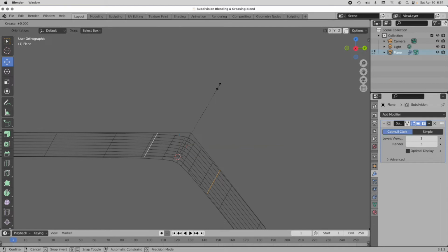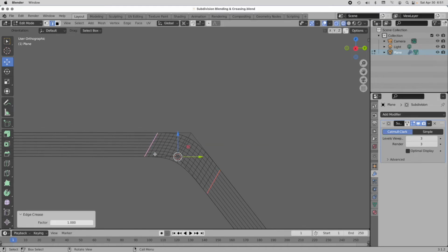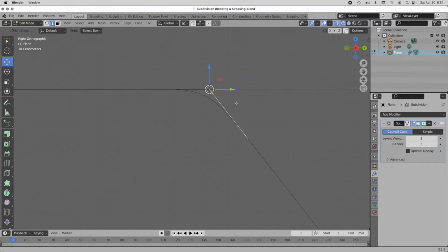So I'm pressing Shift and E, and you just mouse until you see those subdivided polygons only sitting within the original domain of the original parent polygon that they're being subdivided from. They're not passing that hard boundary. And that's exactly what we want right here. We can see that we've got this very well controlled. They're not passing these points that we've put the hard edge crease in. Okay, so our planar region is exactly planar.